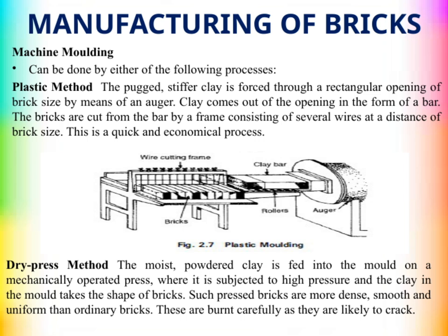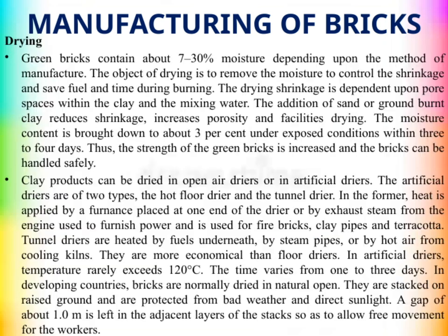Both of these methods are integral to modern brick manufacturing, helping us produce consistent, high-quality bricks efficiently. Let's talk about drying, an essential step in brick manufacturing. Green bricks typically contain about 7 to 30% moisture, depending on how they are made.